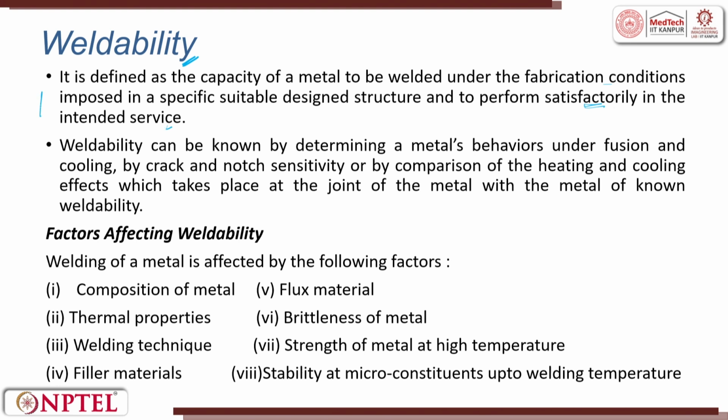Weldability can also be known by determining a metal's behavior under fusion and cooling, by crack and notch sensitivity, or by comparing the heating and cooling effect which takes place at the joint of the metal with a metal known for weldability.